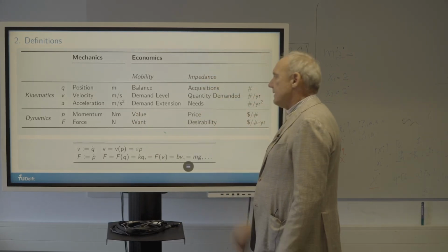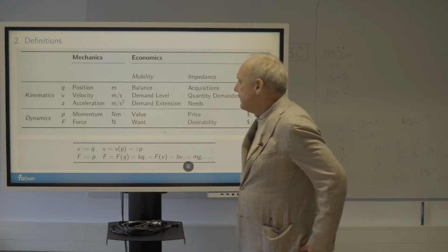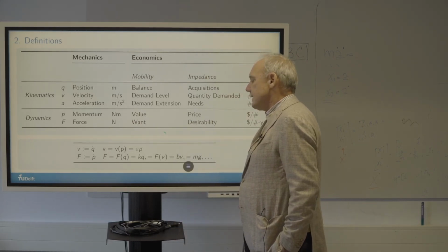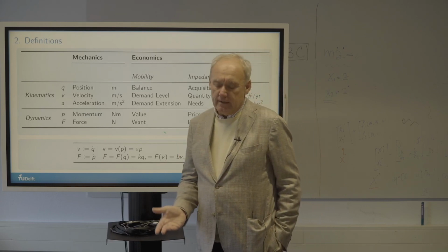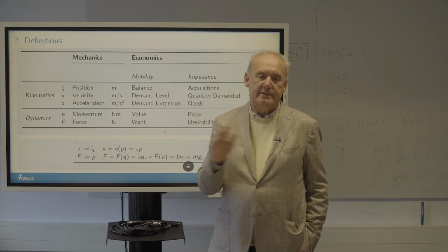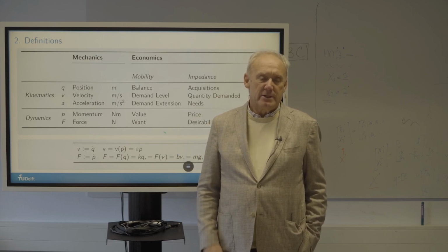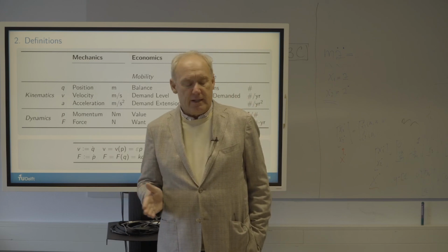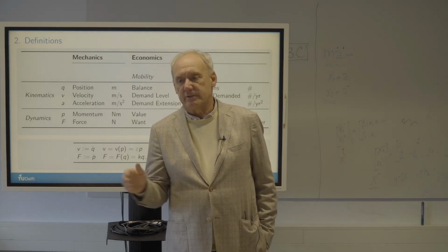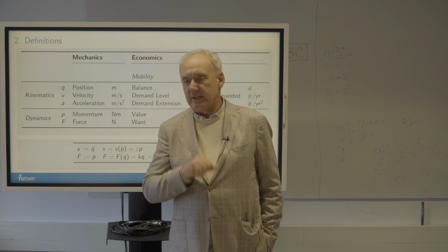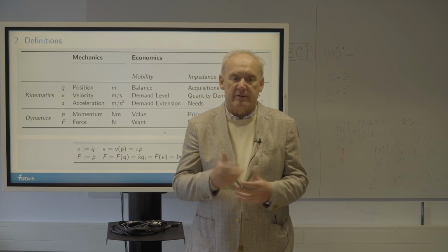In the impedance analogy, everything goes a little bit differently. It's a little bit unfortunate that Maxwell had to take the analog to a mass to be an inductor. Had he taken a capacitor, everything would have been the same, but he did it. So we think of the analog to velocity as an electrical current, not as a change in the magnetic flux, which would be the voltage. Because of that choice, everything turned around.